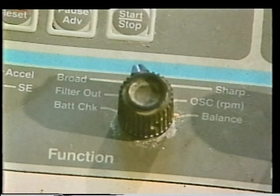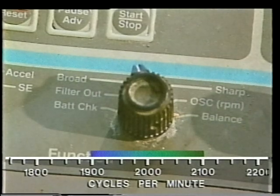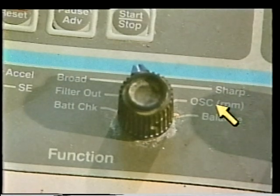When filtered readings are selected, the analyzer examines a certain group of frequencies. This filtered group of frequencies is known as a band. When a band of frequencies is selected for analysis, an analyzer will examine the frequency plus or minus a certain percentage. The total area surrounding the frequency is known as the bandwidth. The function switch on this analyzer can also be used to test the condition of the batteries and to drive a strobe light at specific frequencies.